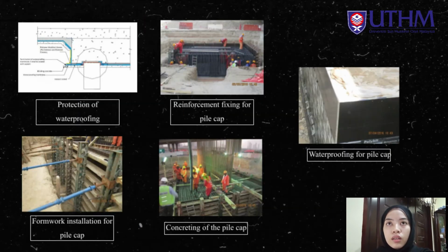Next slide, continue for pile cap installation: protection of waterproofing, reinforcement fixing for the pile cap, formwork installation for the pile cap, concreting of the pile cap, then the last one is waterproofing for the pile cap.